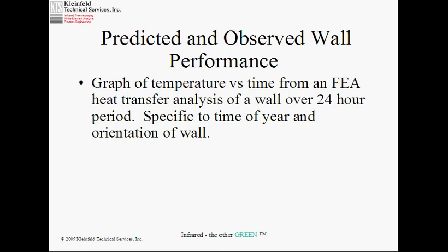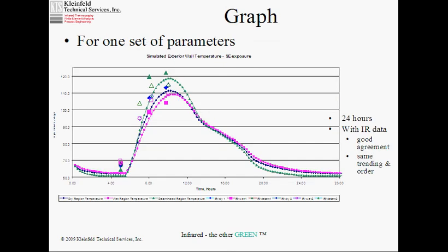And as engineers, you know that the temperature got there by heat transfer, which means that if you do a heat transfer analysis, you can get a handle on what's going on and how it happens and how it occurs. When should you be looking at it? If you saw this, what did it mean? What I'm going to show you now is an example of an output from a finite element analysis for heat transfer of a wall.